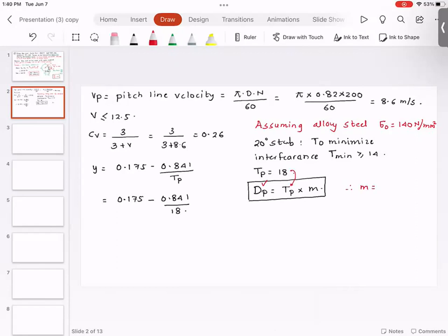So with that, we know the value of module, but we do not know if the gear that we are designing is capable of supporting the torque that is needed, or the tangential forces acting on the gear. So here, the design process needs to be slightly changed, and I will make this a note.